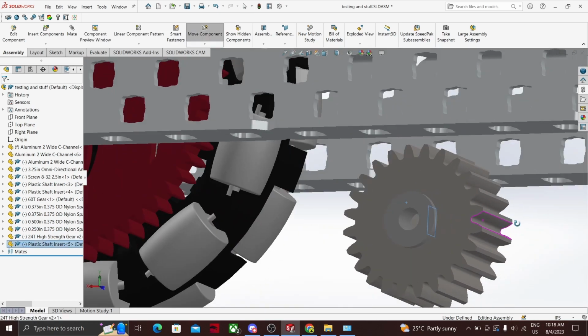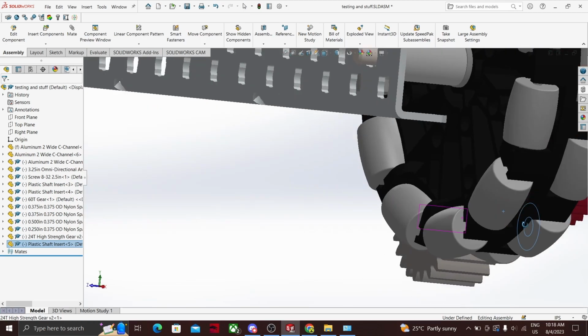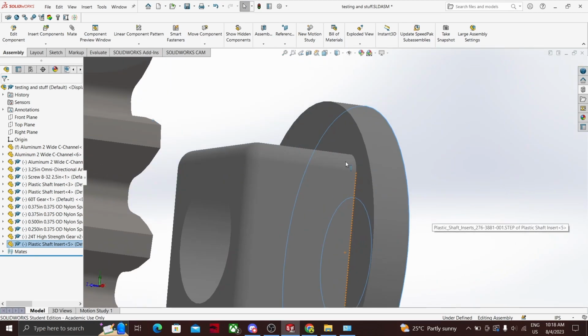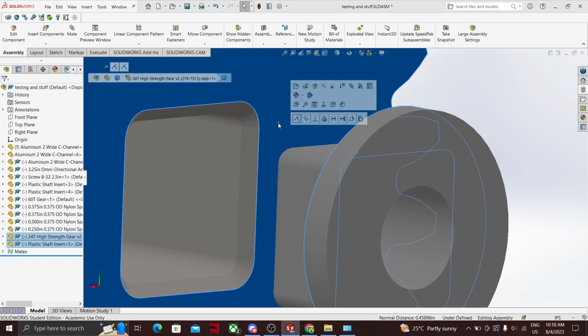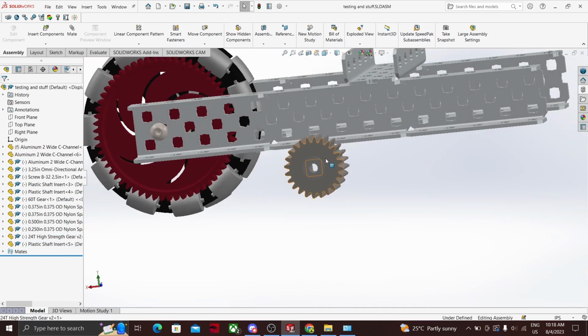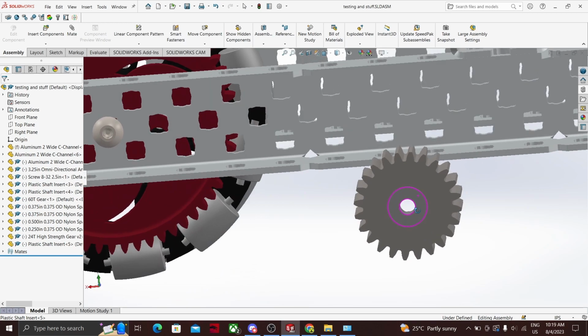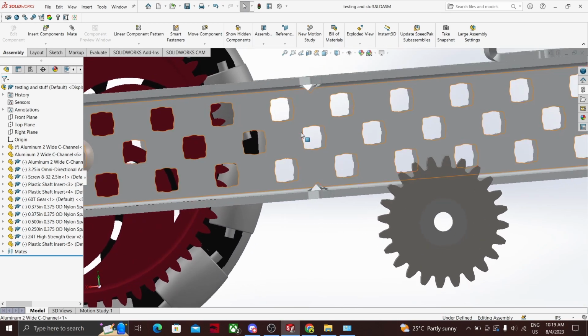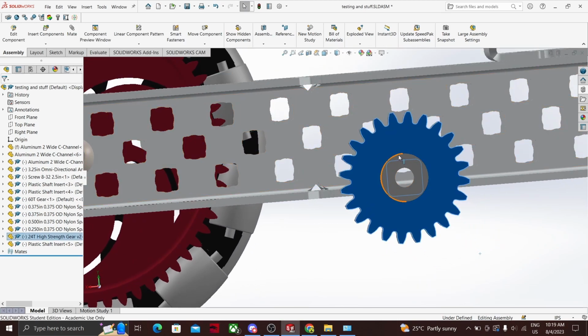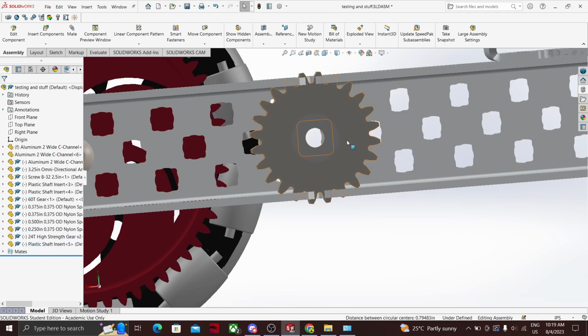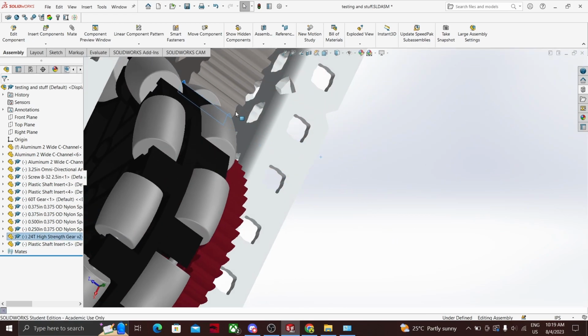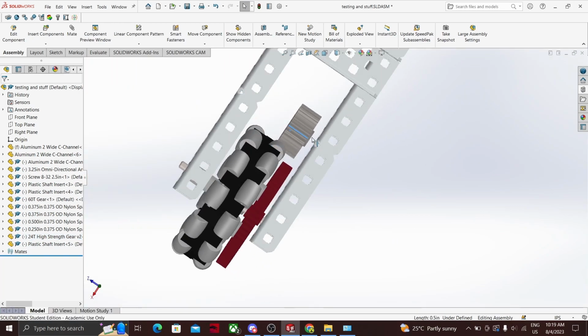Now we're actually in the middle of the gear. And then finally we do a coincident mate right to the end of the gear right there. Now we have a fully defined insert inside the gear, even if we didn't do concentric at all. And with this plastic insert inside, we can actually line it up with these holes now. So we can click one of the arcs on the C channel, and yeah, now our gear is lined up to the C channel and can rotate around it.